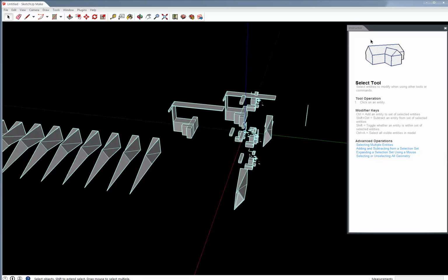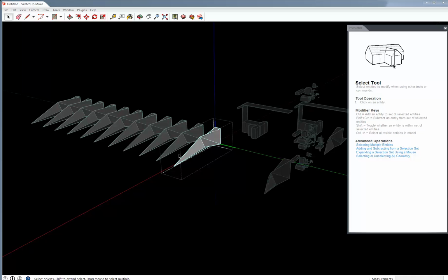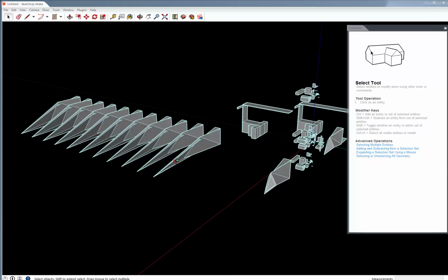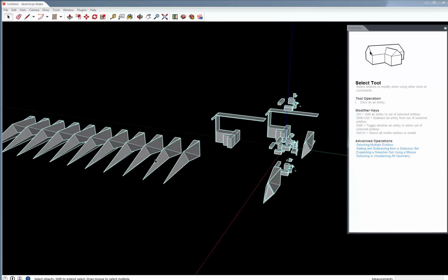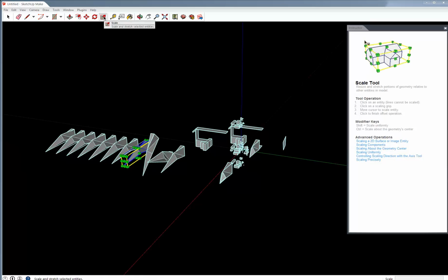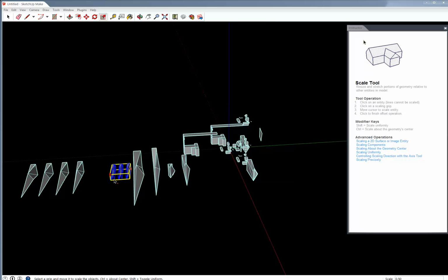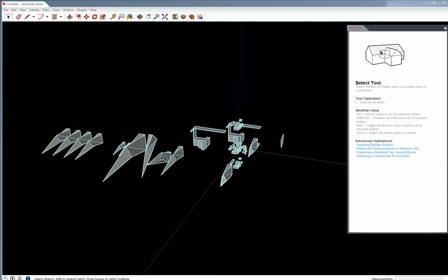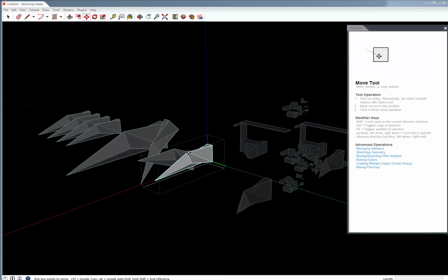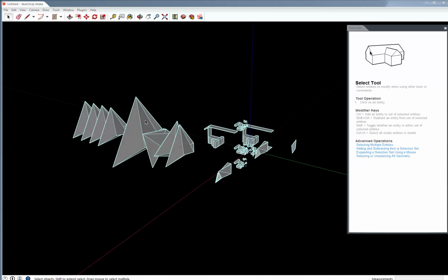Because it's a digital environment we're working in, we can reference the same stuff from memory, but it's just in another place. You can also rotate them differently. If I press move, these little red dots come up. So they can be in a different rotation, or at a different scale, if I press the scale button up here, or press S for scale. Maybe these ones are little tiny versions. So they can be in a different place, a different rotation, or a different scale, but it's still referencing the same geometry inside that component. You can start to see some interesting things happening when they're at different rotations and scales.